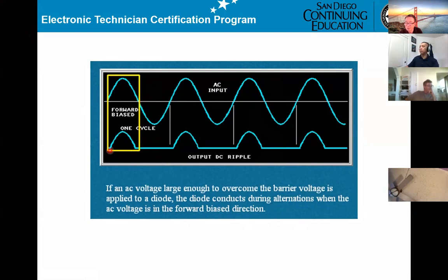So that's why in the output you can get this signal, copied from here. However, when you get the negative part of the sine wave, then the diode will be off. So that's why nothing. Okay? And they keep going. So that one signal coming out here will be half-wave rectified.